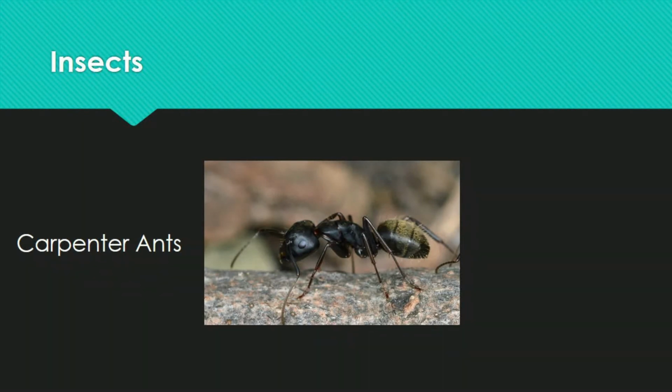Carpenter ants may be found across North America and other parts of the world as well, and they come in a variety of sizes, which helps to determine the colony's age. For example, larger ants would indicate that there is in proximity a very developed ant colony. Carpenter ants are more common in locations where the water table is high, and they make their nests in damp wood and seek high moisture locations in and around wood infrastructures. Before ants start constructing nests, incipient or extensive rot is usually present within the wood of the pole already. Carpenter ants have a black waist and range from around 1/4 to 3/4 inches long.